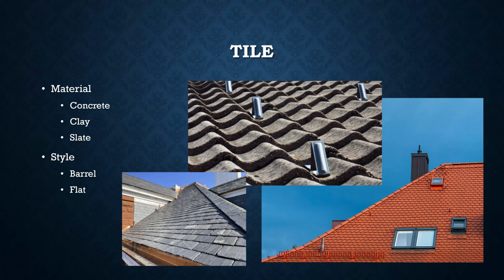They serve different purposes and cost different amounts. The concrete tile is usually the cheapest one, but it comes with lesser longevity. The UV damage is going to break down the concrete. It's not going to look the same. Clay is going to stand up a lot longer. It's usually going to be stronger, not as big of a deal.